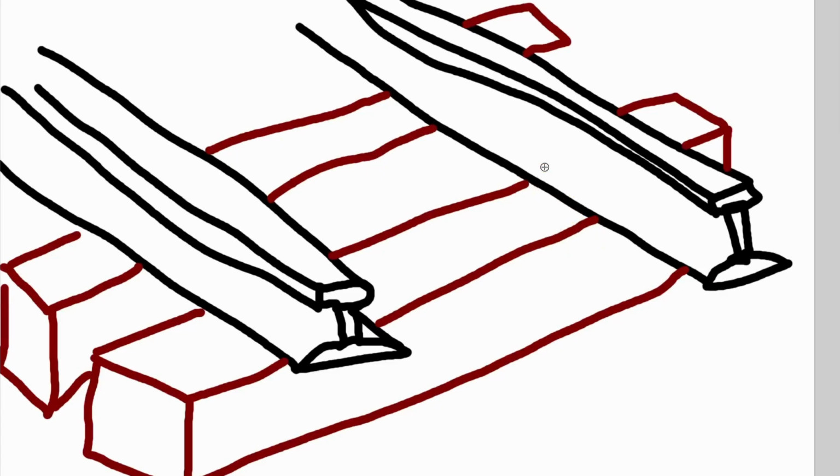But one important thing that is typically overlooked or is not terribly well known by people outside of the industry is that we also have, in most applications, something called a tie plate. And a tie plate is a thick metal plate that aligns the rail. It has little feet, and it has holes drilled in it for where the spikes go, so we're not just randomly tossing things in.